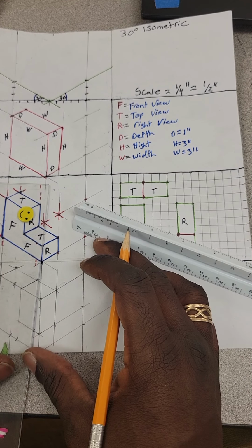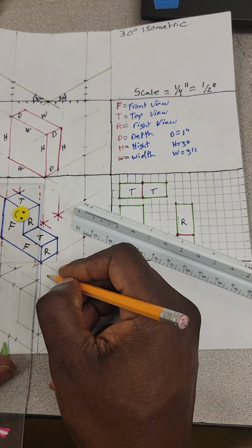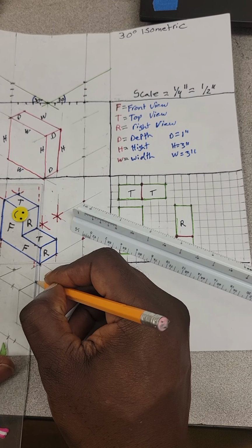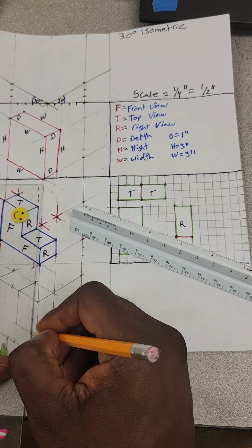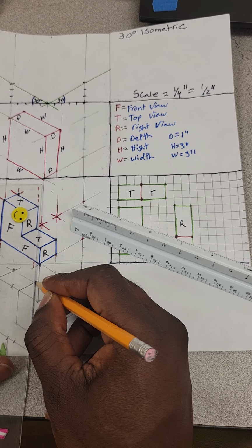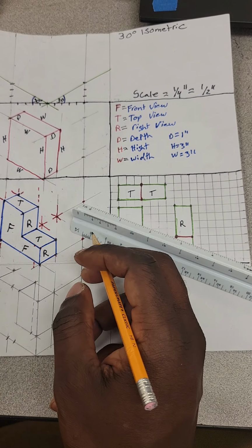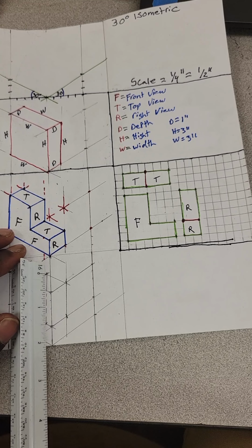I'm going to create that imaginary line. Punch your pencil there to help you out. Light line going down. I call it a hidden line at this point. That's going to be a solid line, because this line right here is going to go away, but we're trying to get this line in the back. So then we're going to measure up on that line 1 inch.